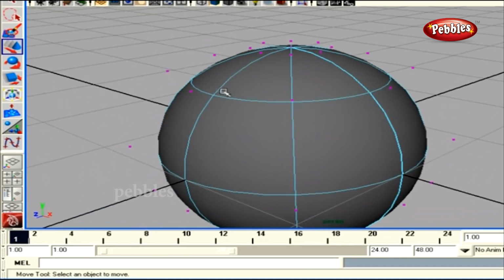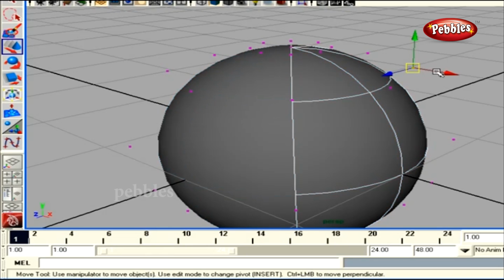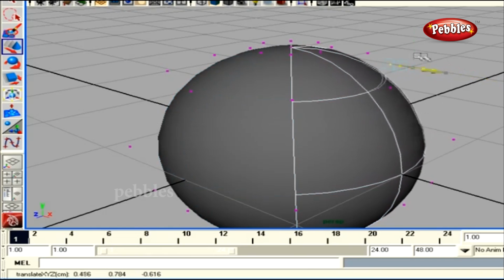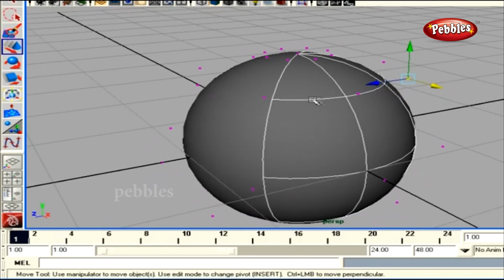Now, if you remember, I clearly defined that NURBS surfaces are made of curves. And here the control vertices are placed at a distance very, very similar to the control vertices of curves. And why shouldn't it be? Yes, of course, it's made of curves. If I just select any of these vertices and transform them, watch, I can transform the shape of this object. But in fact, we are transforming this curve through these vertices, which in turn transforms the object.